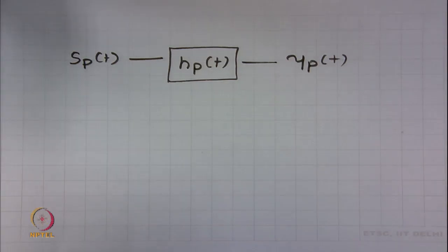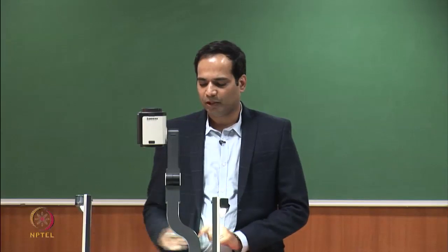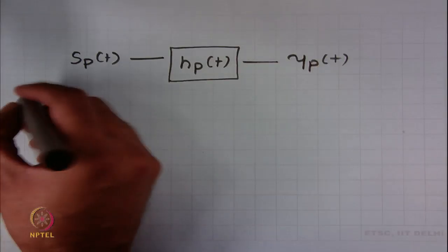Now, I do not want to design this filter in passband domain. Designing this would involve making analog demodulators or modulators, and this would be complicated, and we would like to do everything in baseband domain. So, we would like to make this filter in the baseband domain, and today we will see how we can do that. So, the idea is